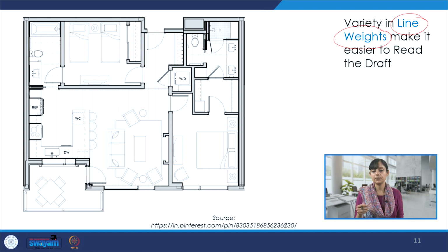And this could also happen manually when we do the sketching, whether we are using a light intensity pencil or a dark intensity pencil, whether it's like 2H, 4H, 2B, 4B, 6B. So H is the lighter one and towards B is the darker one. And then with the combination of light and dark, we could create this kind of a variation.